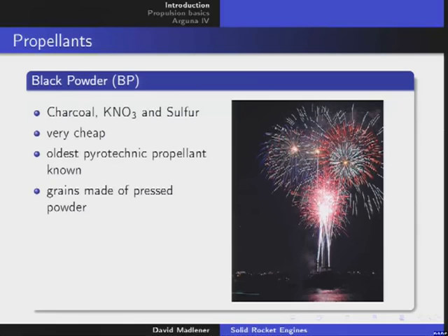So you take the ingredients, you grind them down, you press them into a grain, and the problem is, of course, this stuff is very sensitive to electrostatic discharge and so on. And all of you have heard about powder mills blowing up and so on. This is very dangerous stuff, so don't do it at home. Let professionals do it. Because the grains, because they are made of powder, are sensitive to cracking, of course. There's no binder in them, so they cannot hold just by the adhesion by the pressing.